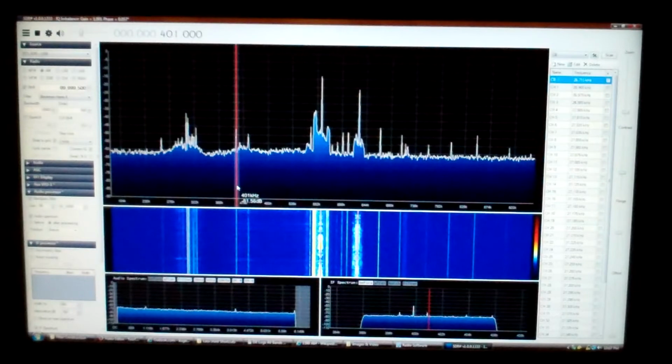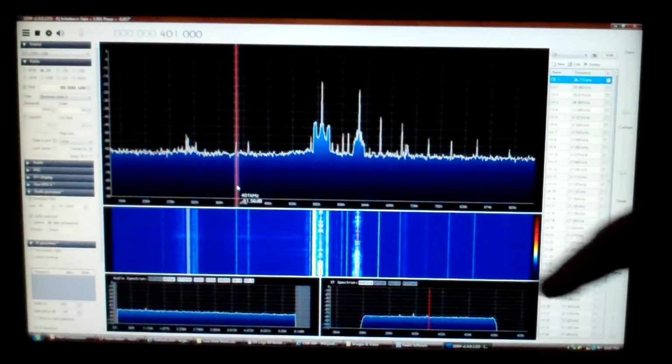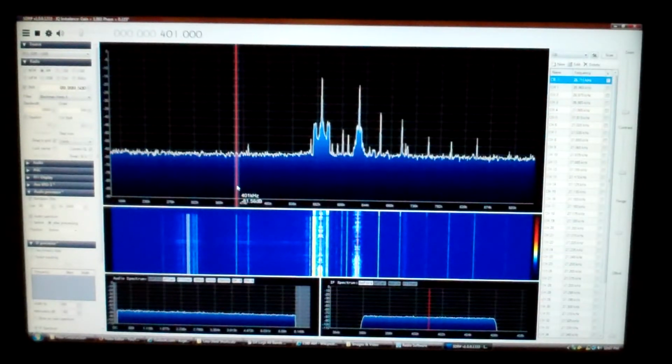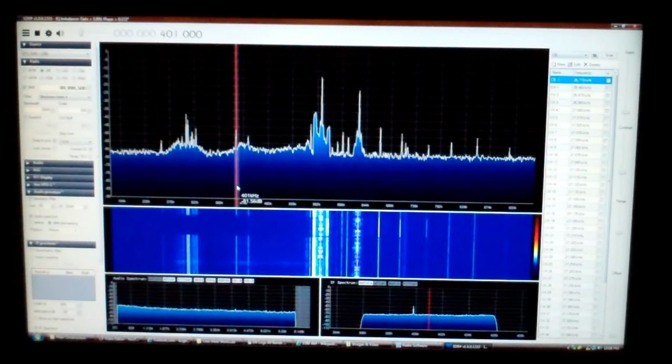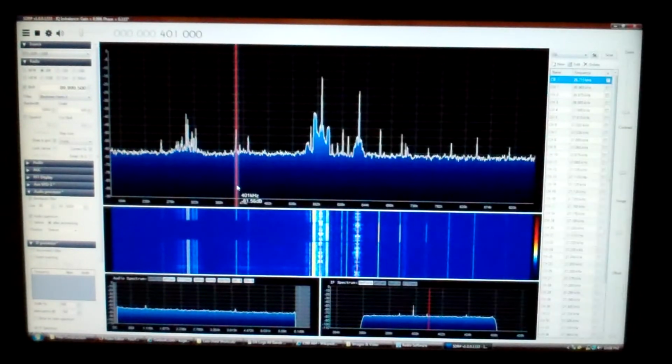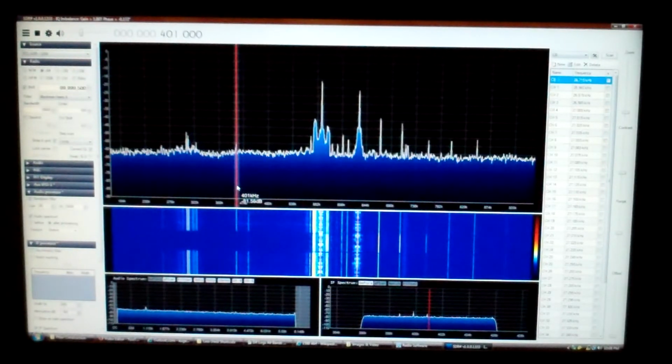And you can barely hear a 401 kilohertz NDB in the background. But when I put the 520 kilohertz high pass filter in, all the long wave band almost completely disappears. You can still see the AM band here. Looks pretty good. And if I take the filter back out, there comes the whole long wave band with the NDB. And also there's a lot of lightning tonight, which is what these little poofs are in the long wave band. And the 520 kilohertz high pass filter is also eliminating the static from the lightning.